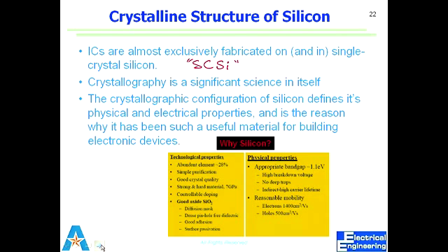Too small of a band gap would mean that it will be very easy for electrons to jump into the conduction band, right? That kills my semiconducting behavior. So it depends on application essentially.